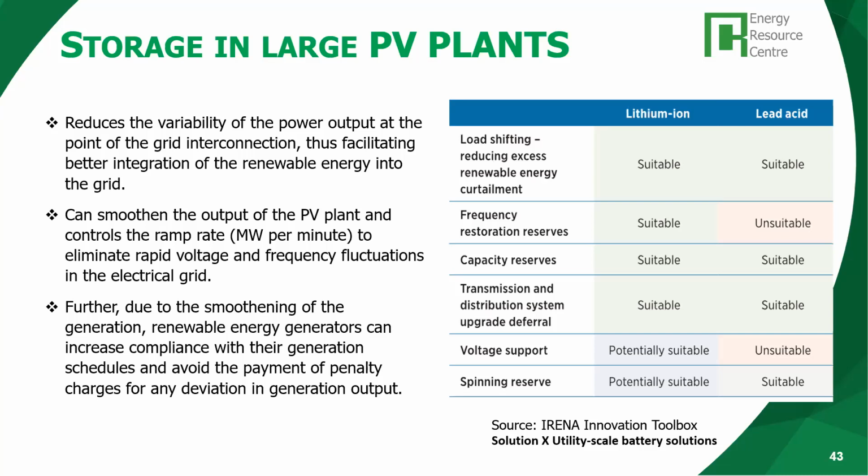Essentially, lithium-ion batteries are very suitable for ancillary services related to PV plants and solar farms, but lead-acid batteries are also suitable for some of the services that PV plants may need, like load shifting, capacity reserve, upgrade deferral, spinning reserve, etc. So again, lithium-ion and lead-acid, together with other technologies that I didn't put here, like flywheels, sometimes flow batteries, but very large ones.